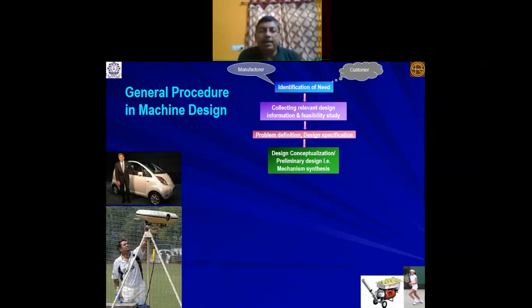If the wheel rotates at high speed and the gap between the two wheels is slightly less than the diameter of the ball, then once the ball touches the wheels, if the angle of bite is proper, it will drag the ball and the rubber portion of the wheel will squeeze because of the small gap, and it will just throw the ball in a forward direction.